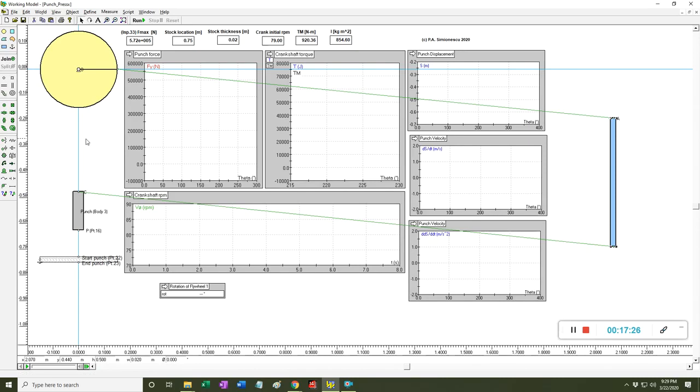You saw what I did. I took the connecting rod out of the assembly. I typed for the angle 0, and this is a confirmation that when I generated the link, what I actually did was I drew this way. The better way of doing it is to draw it like so, and then you rotate it. So let me make the change. I'm looking at the height is 0.5, and I'm going to just change this. So I delete this.